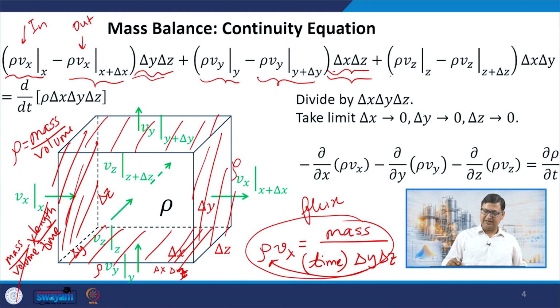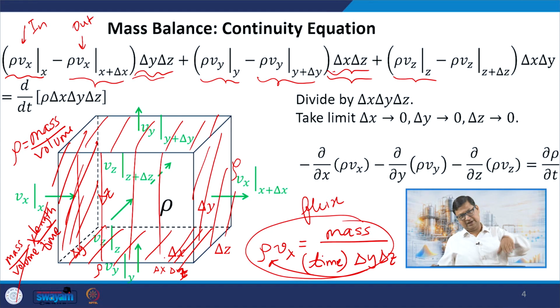And the same argument I can apply also for the phase right here, that is into the plane, into the slide plane I am showing here. This is the inflow, and outflow happens from the behind of this, right. So, this becomes my in, and at z plus delta z becomes my out, right. And then I apply standard calculus whichever I have used earlier, but before that what I am doing, in minus out is equal to my accumulation.